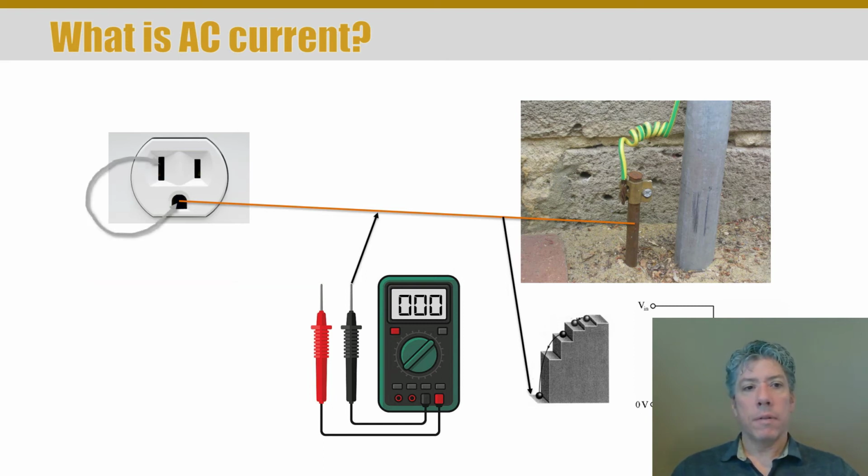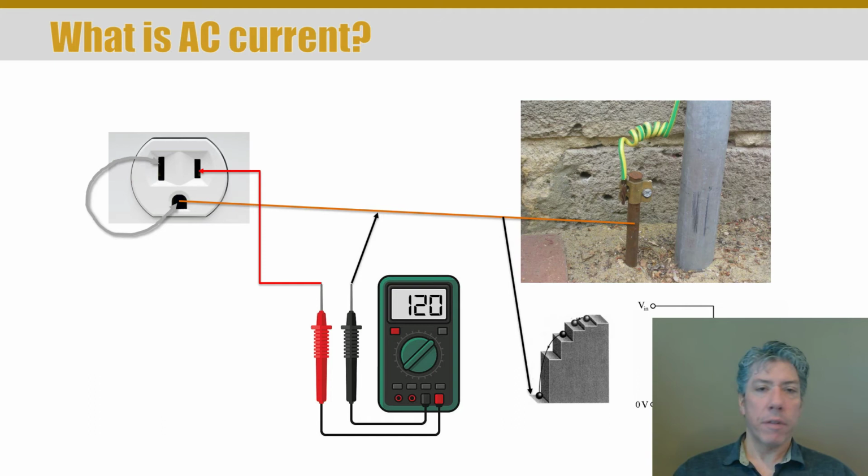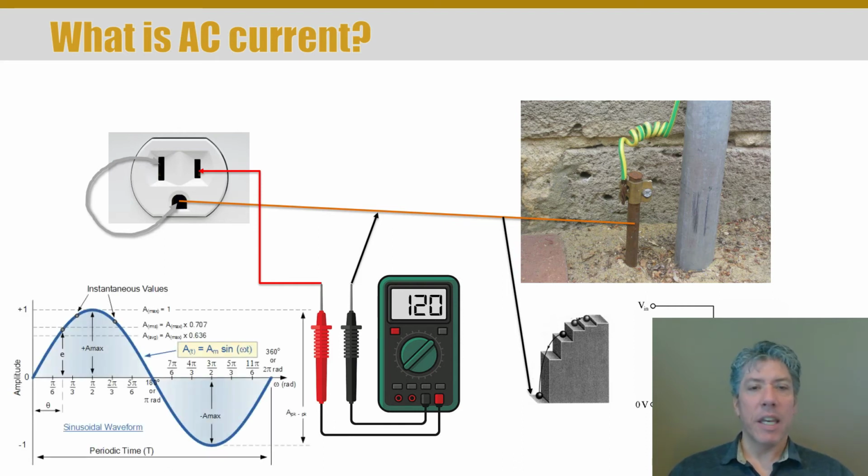Well, so that's just illustrating those two are connected. What if we put the lead in finally the other one? Well, that one's called the hot leg. In that case, you'd get the 120, 115 volts AC, whatever it happens to be. It does vary a little bit. But you'd get high voltage. This is the one that can shock you. Okay, this is the one you don't want to touch. And don't touch any of them because it could be wired wrong. But this is the one that would certainly tend to shock you. It is the smaller blade side. Again, assuming that the house is wired properly.